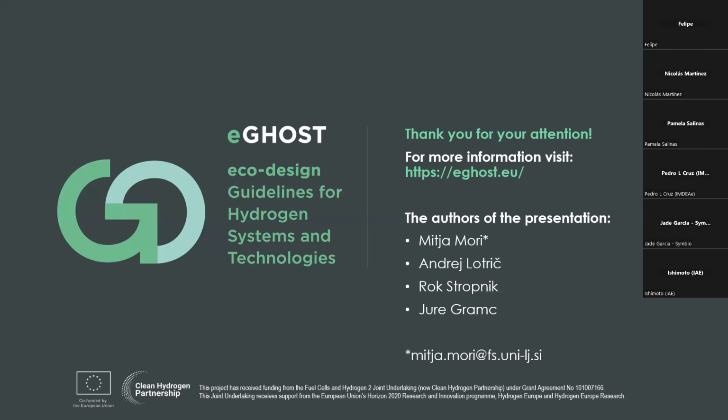A bit different is the solid oxide technology, since we don't have the exact generic databases of the virgin materials. I'm talking here about maybe yttria-stabilized zirconia and other ceramic materials. We are very much focused now on establishing as exactly as possible the virgin production of those rare earth materials, but they are a few orders of magnitude lower on the scale of environmental impacts per same mass unit than platinum. So the recycling of those looks promising, but should, of course, be even more carefully addressed. Because in recycling, we want to get at the end a recycled material that has lower environmental impacts than the virgin one.